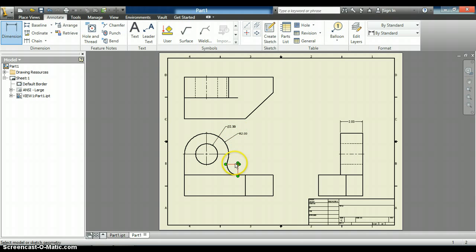We've already got this center mark and this one here, so we need to do this radius as well. So in this case we're going to click down here and draw our radius. You'll notice that it automatically puts the radius through this center mark because this is an arc, and in this case we don't have a lot of space to work off of. Normally we would want to put it between here as our first option. However, that makes it a little bit crowded, so we are going to move it up a little bit just to get it out of the way.